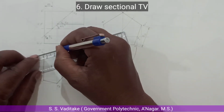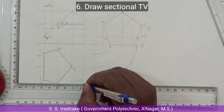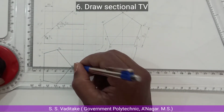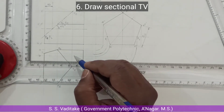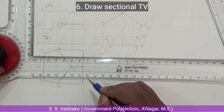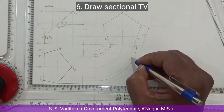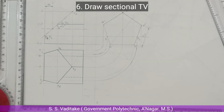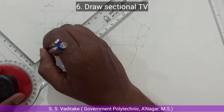where the sectional top view will appear. Now finalize the remaining portion in the top view by means of a continuous thick line. Now see the edge B is partially hidden, so it should be represented by a dotted line, as well as edge C is also represented by a dotted line. So edges B and C should be shown by dotted lines.